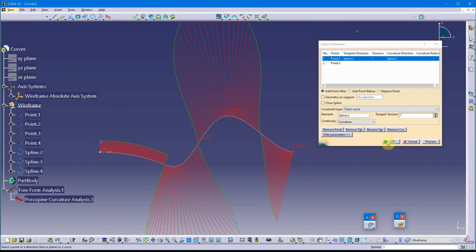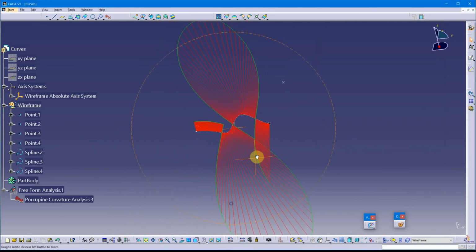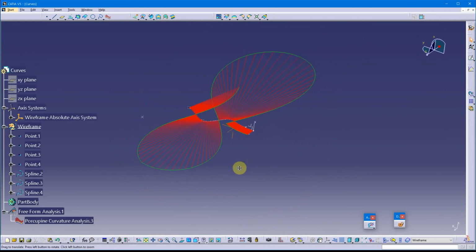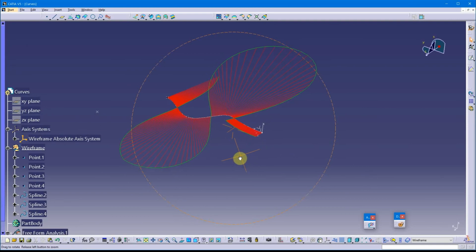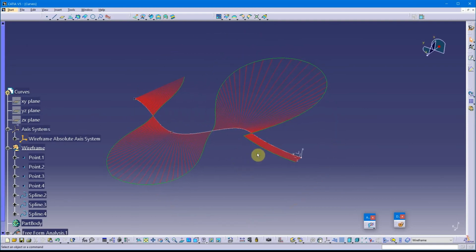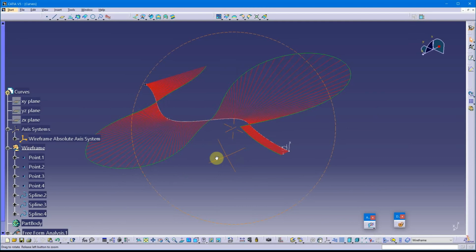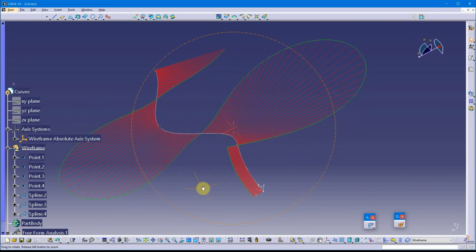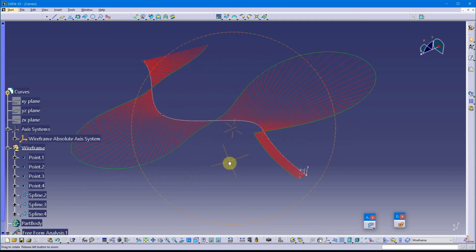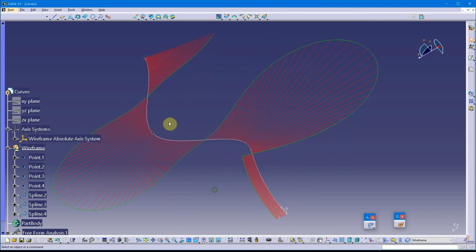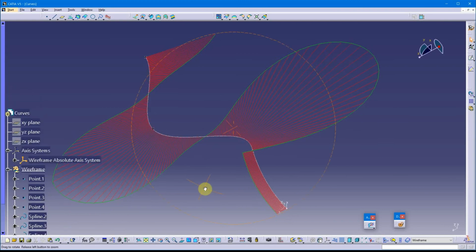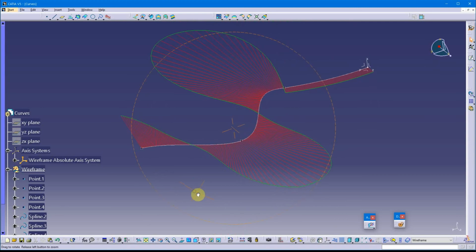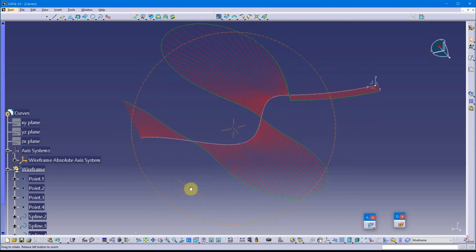So for Class A surfaces, and I'll get into Class A surfaces more later, essentially a Class A surface is a surface that's visible by the user when the product is in use. You can think of an automobile, it's most of the body of the car when it's in use. So the doors are shut, the hood is shut, etc., and you can see the reflection. So Class A surfaces typically will be G2 or better. That's usually going to be based on company standards, but that's the standard I like to use in my classes. It's G2 or better, and it depends on the product.